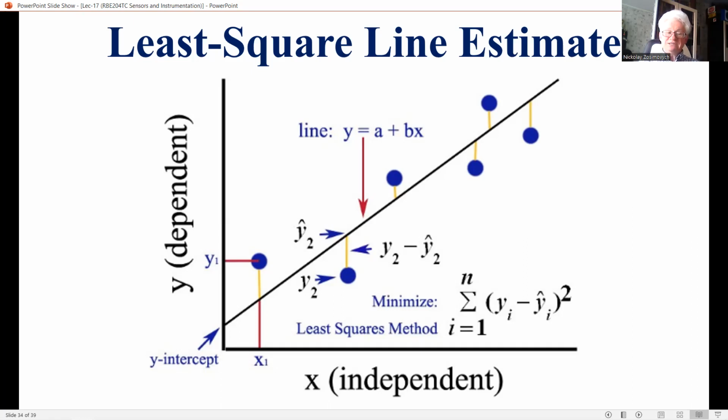In the context of sensing and instrumentation, it is also known as the mean calibration curve. Instrument linearity may be represented by the largest deviation of the input-output data from the least squares straight line fit of the data. So least squares estimation, or LSE, comes under the general subject of model identification or system identification.